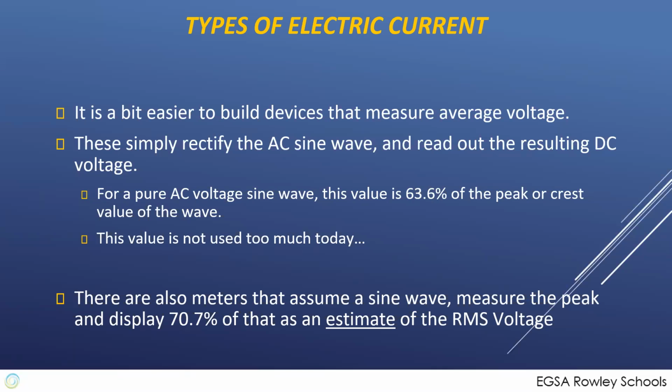So the point of this is make sure that you have a good true RMS multimeter, because anything else is going to have your values off. And especially if you're doing anything in field operations where you've got a large amount of resistance coming in from cabling and the like, that difference could be enough to affect the ability of the equipment at the far end to work properly.